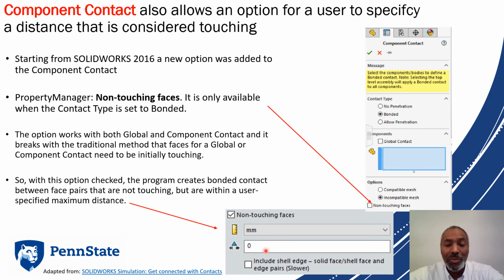So it's a very useful tool, and it can probably save you a whole world of hurt if things are turning up not bonded when you want them to be in your model, because maybe somewhere in the definition of the drawing a geometric relationship was not set correctly, or maybe there wasn't one set at all that would have tied those things together.